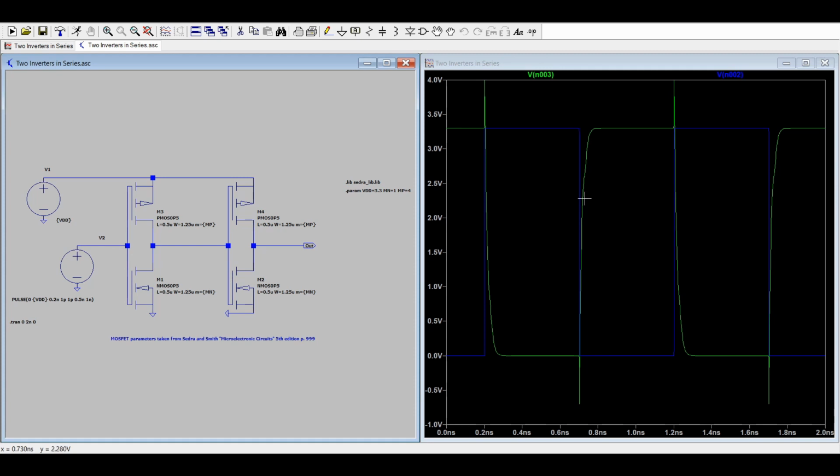Let's have a look at this one here. When my input goes from a logic 1 to a logic 0 in a nice beautiful way, because it's generated digitally, via computer simulation I mean, the output voltage suddenly zooms down to a negative value and then rises up slowly until finally becoming the correct value at the output here. And then at the next transition, the output shoots off up to 4 volts and then slowly drops down until becoming the correct 0 volts.